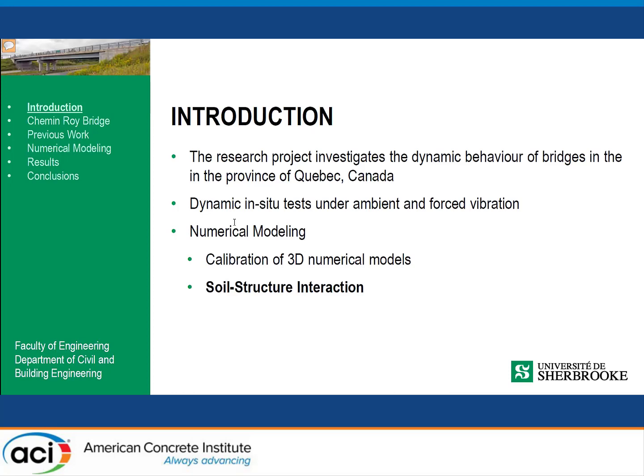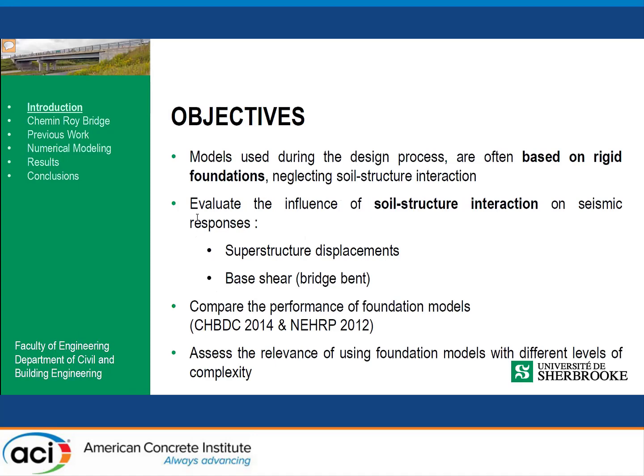Then we compared it with the method from the US National Earthquake Hazards Reduction Program, the NEHRP 2012, which is quite similar but includes damping in the model, just for comparison purposes. Here in Quebec, which is a low to moderate seismic zone region, in practice the engineers will model on rigid foundations.